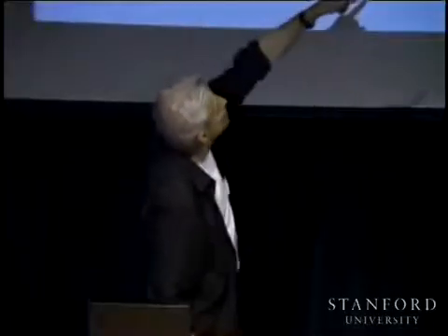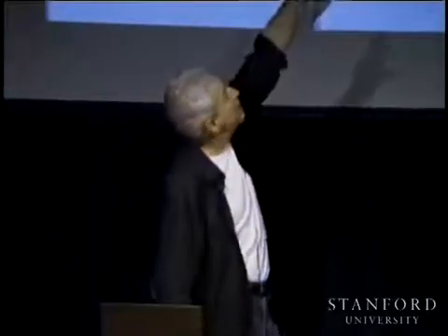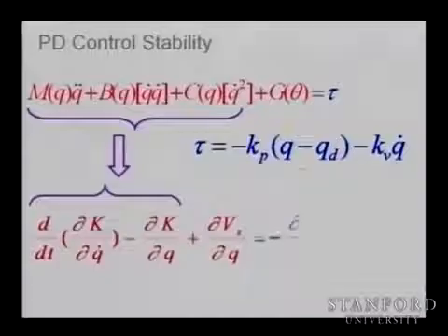And what we're going to do is go to that first equation in the matrix form, and we are going to take a torque that is proportional to the mass matrix. So our torque will be some estimate of the mass matrix times torque prime, plus a beta that compensates for V and the gravity. And this is what we're going to do.